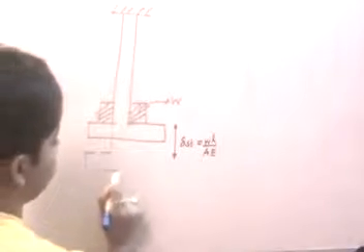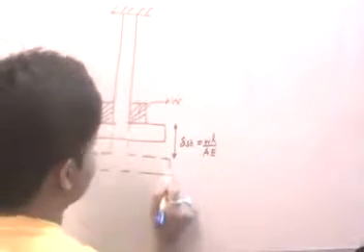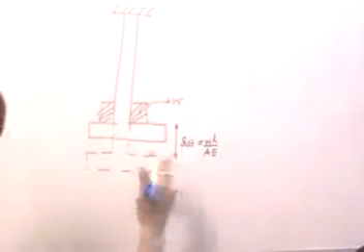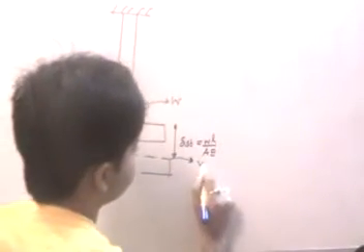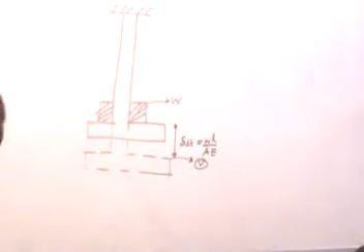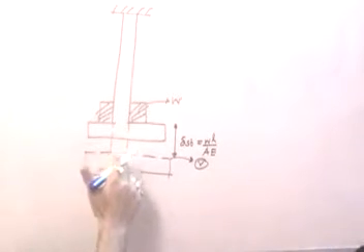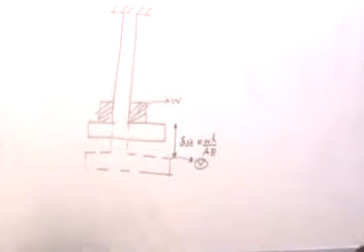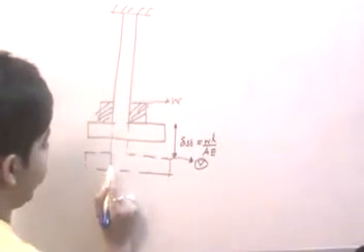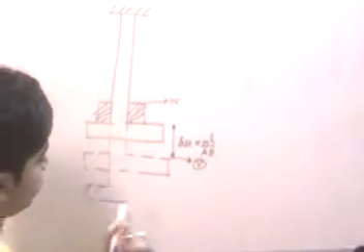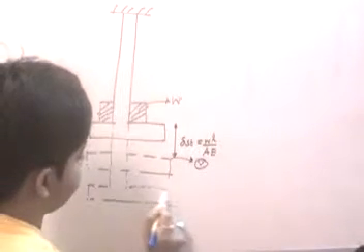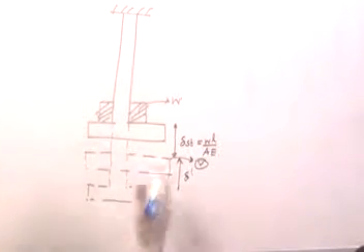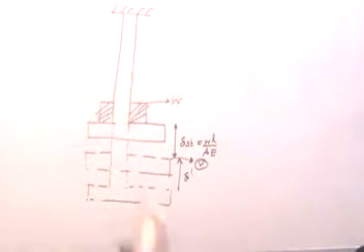Now at this point, what basically happens is that the potential energy that this body had is converted to kinetic energy. So at this point, this body will acquire some velocity, and as we know, if the body acquires some velocity at the point, so essentially this velocity or this kinetic energy will be strong enough to drive the body through a deflection, right? So essentially will drive the body to some sort of a deflection, and let's say that this deflection is delta dash. Now whether we can find out delta dash or not, we will see.